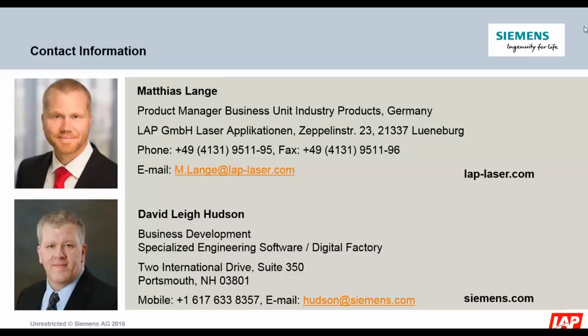They'll use laser projection to project the area where someone is supposed to lay those tows up to achieve the boundary that can't be achieved by a particular machine. That's really where the LAP solution comes in: we've got an area of this particular layer, that area can be defined, and then based on that minimum course distance, it can be generated as its own separate manufacturing data set and sent to LAP for projection, so somebody knows where to lay that up and accurately lays that up.